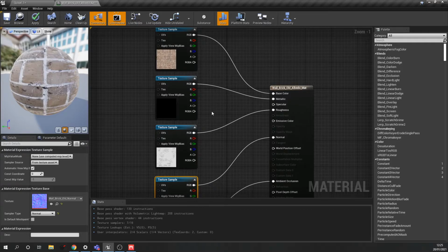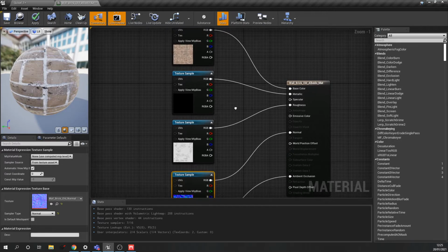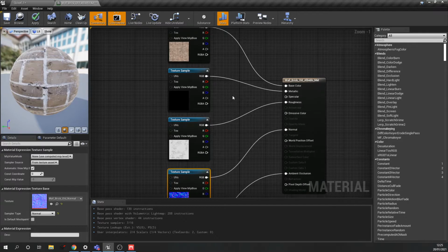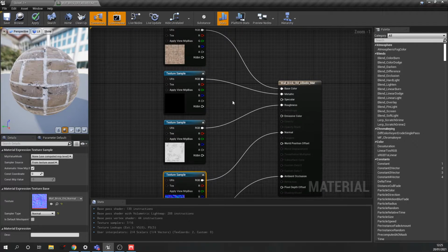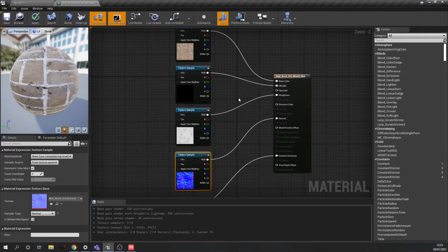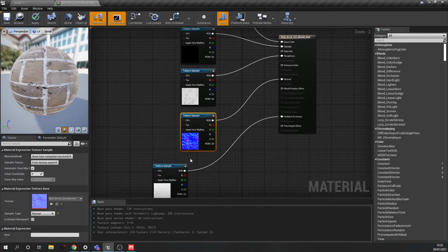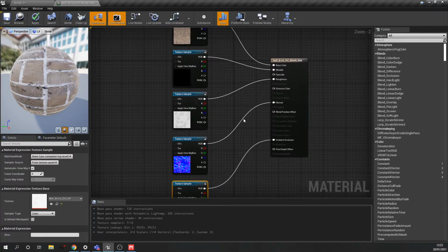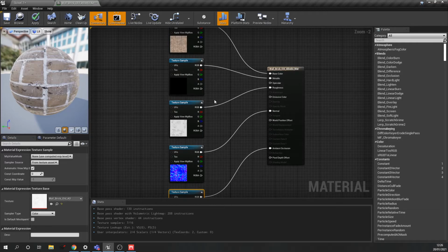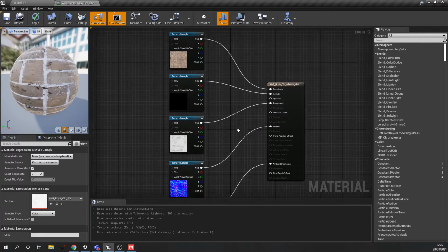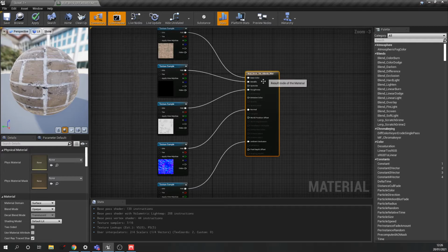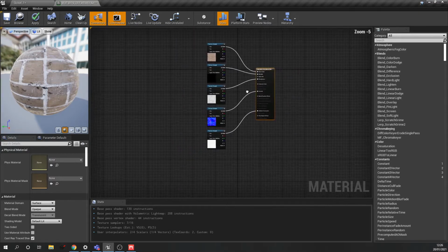I believe you probably could just plug the gloss into, I can't remember off the top of my head if you plug it into metallic or roughness, but you plug it in and then you add a different node to it as well to make it do its job. So you can do it. You can get Unreal to follow a specular workflow by using specular and gloss instead of metalness and roughness. But if you have the option of metalness and roughness, then why bother?